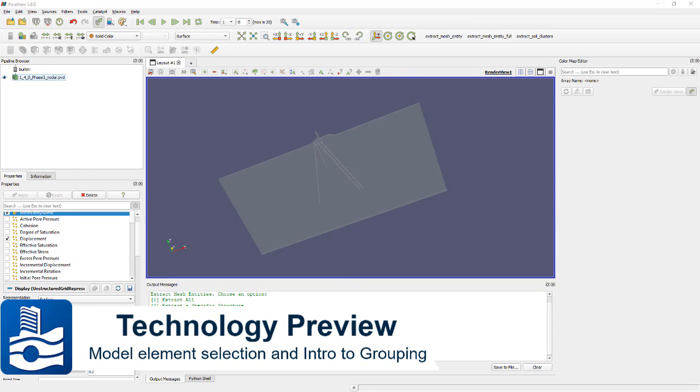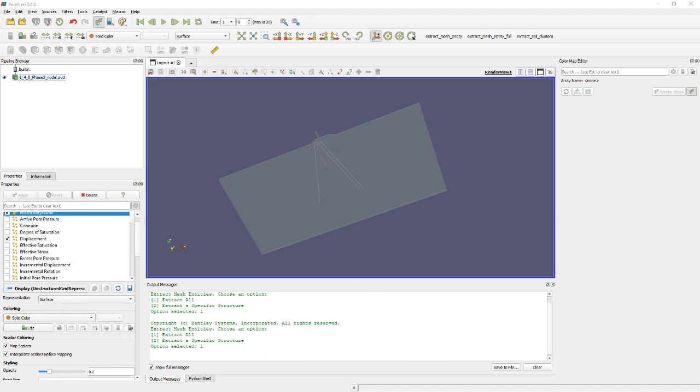In this video, we will present how to use ParaView for advanced model rendering for optimal results, Plaxis result presentation with a special emphasis on advanced selection. We do have here a Plaxis model representing a high wall on a levee with the following constitutive elements: the foundation wall, the sheet pile wall here, and battered piles with H profile beam.